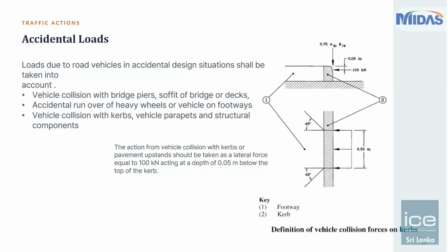It will not always be the case that a vehicle hits your crash barrier on two sides equally, right? They can hit either on the left side or on the right side. And when it hits, obviously, you will have some kind of torsion generated in your resisting system. Okay, so your box system should be rigid enough to take that. Obviously, you'll see some base pressure increment on one side, and you'll have some reduction in the base pressures on the other side. But because we have a base slab with a box, the resistance to these minor lateral loadings would be quite huge.